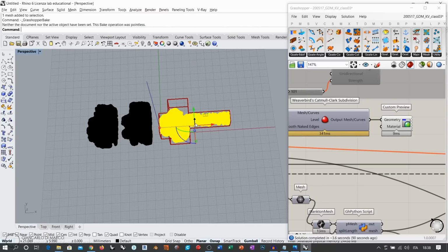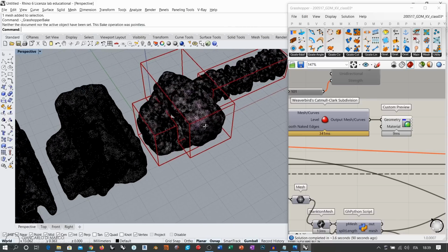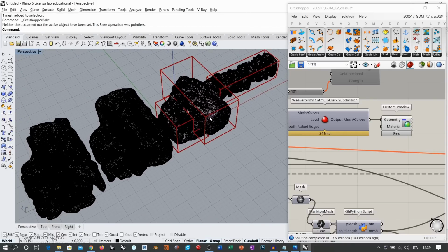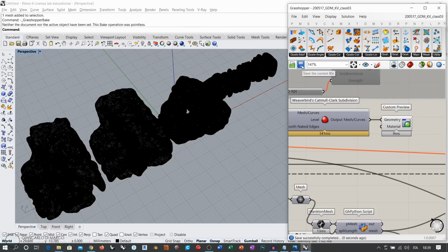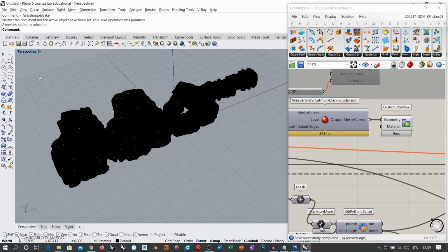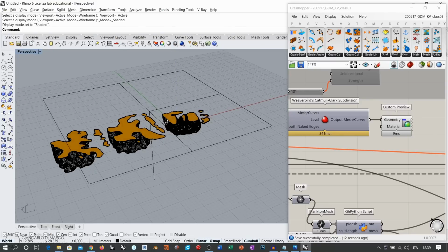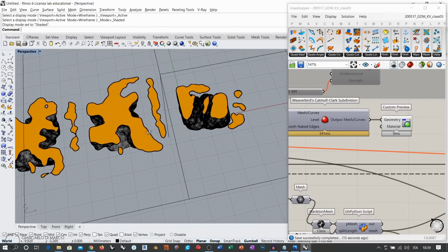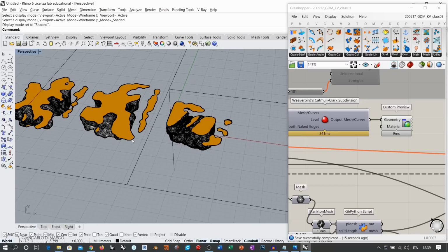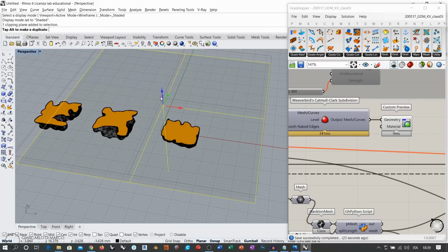One thing that you might want to double check when you work with these algorithms is that the result that you got is, well, actually regular. So you might want to turn off Grasshopper Preview and analyze these objects. For example, I normally use a clipping plane, like in this case, whatever orientation is good. Go into shaded mode and you will see the intersection or the sections of these objects. And so if you take the clipping plane and move it, you should never see